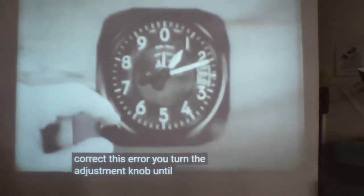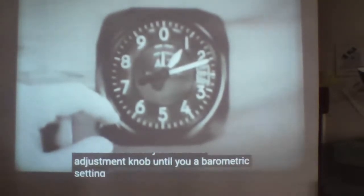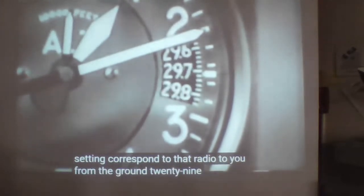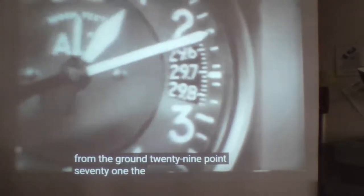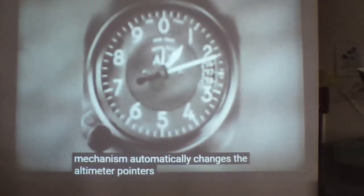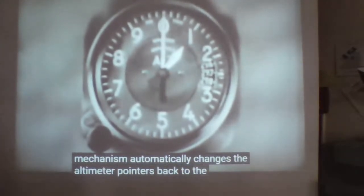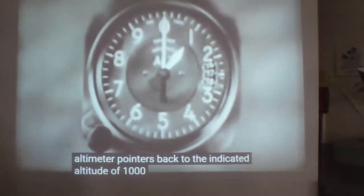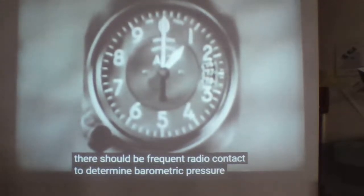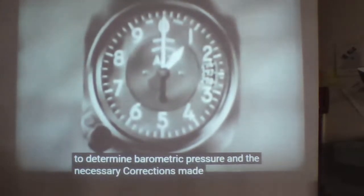To correct this error, you turn the adjustment knob until your barometric setting corresponds to that radioed from the ground, 29.71. The synchronized gear mechanism automatically changes the altimeter pointers back to the indicated altitude of 1,000 feet. During flight, there can be frequent radio contact to determine barometric pressure and the necessary corrections made.